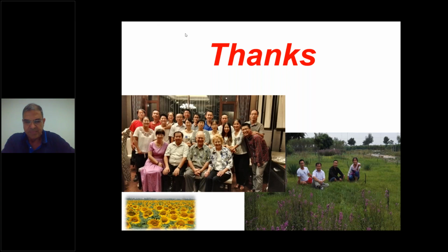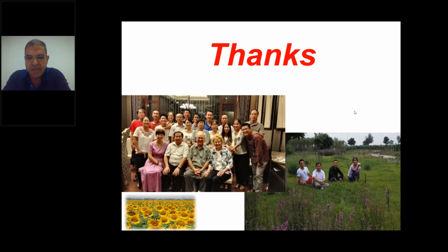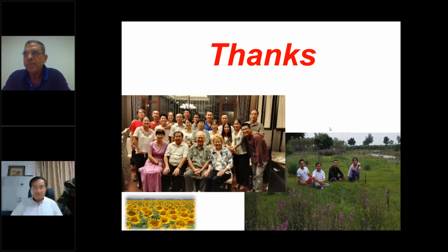Dr. Wawa, please. Yes, I think today this presentation is very interesting for all of us, especially for African countries. As you know, we are sharing the same conditions, similar to what Professor Kang mentioned, in arid and semi-arid areas, especially when you are going to use saline water and also for saline soil. And the most important thing now, the main key, is how we can control the moisture in the soil. By this way, we are trying to keep the soil moisture within a range, not to reach the wilting point and to be under the field capacity limit, which is not to reach saturation.